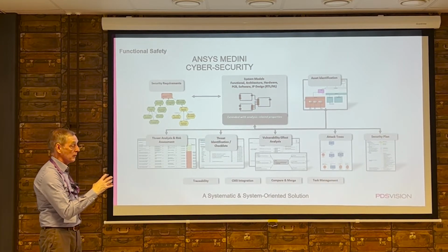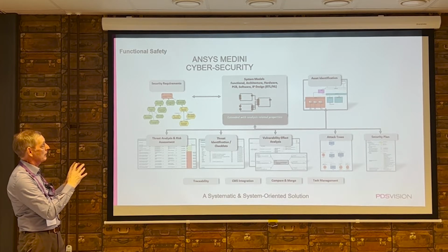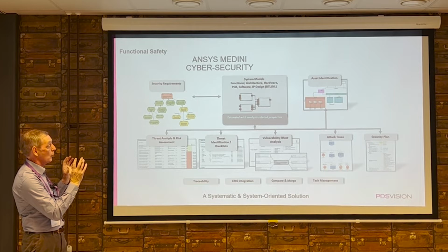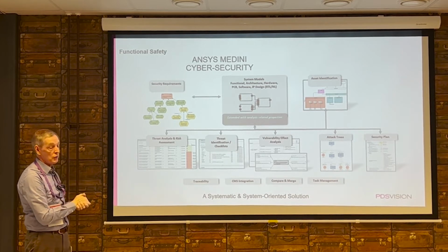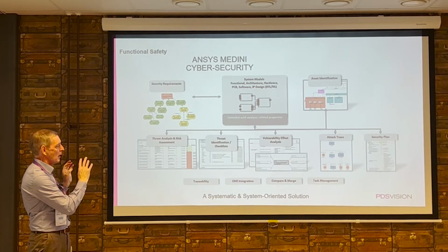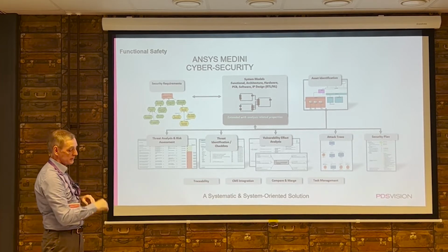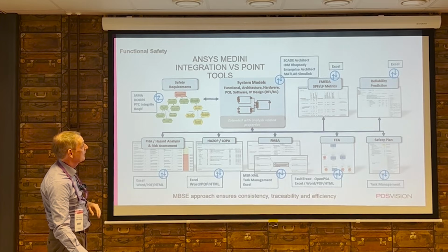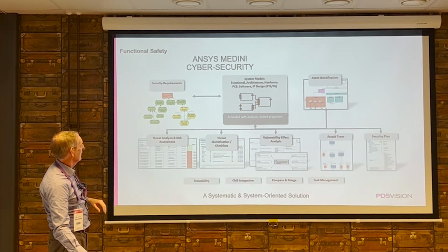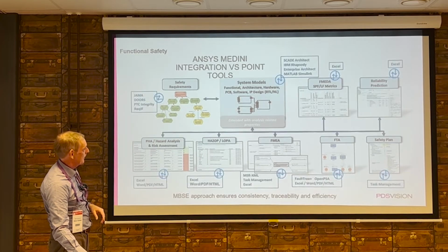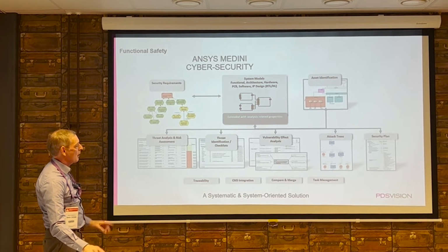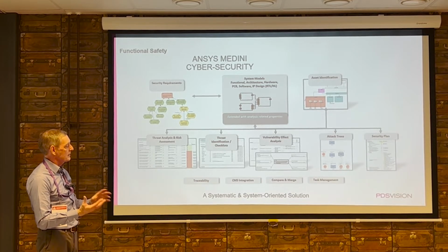It also covers not just the functional safety side of things, but it also looks after the cybersecurity element. So you can simulate and model your cybersecurity performance. So it's a common approach, common structure, just different terms. For example, whereas before we had FMEDAs and reliability, you've got asset identification, where you might be looking at attack trees there. You're looking at FTA, which stands for fault tree analysis. So there's a lot of commonality.